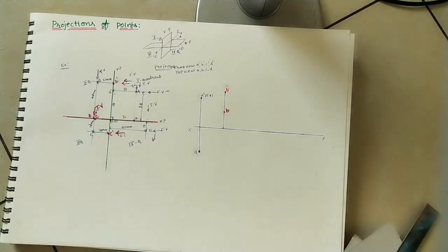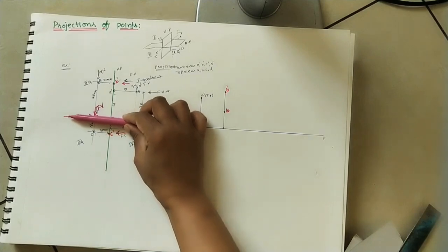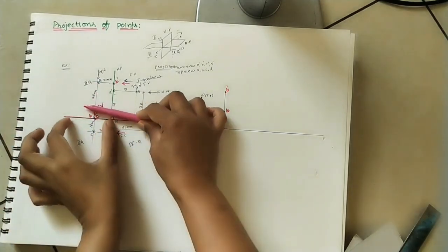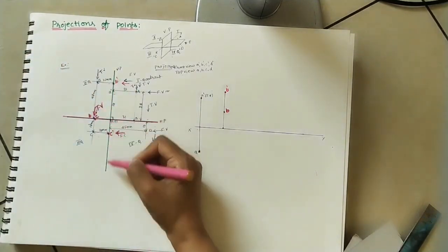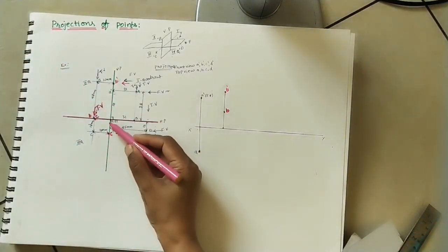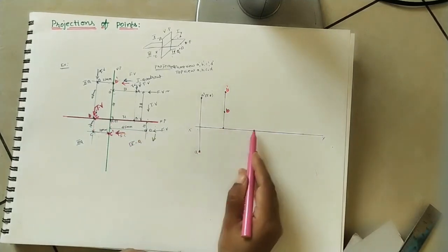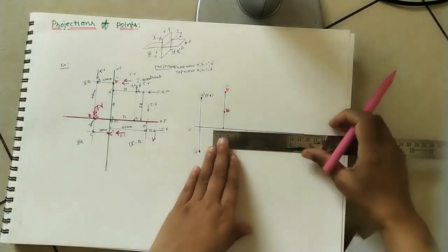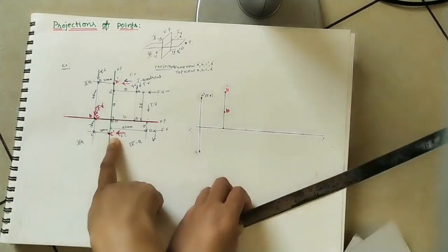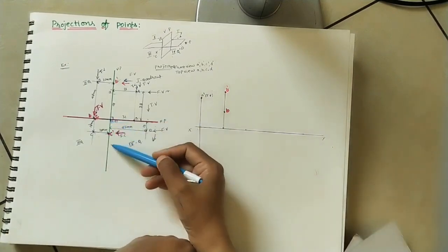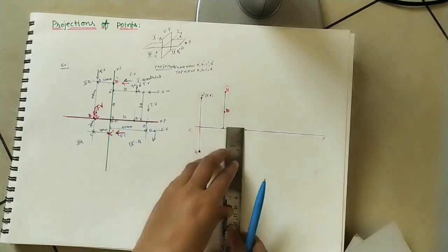So for doing the 2D view here, what I told, we are tilting this horizontal plane in clockwise direction. This part will move in upward direction like this. Okay, this plane is as it is. So C dash we have to mark same as it is. How much distance is it? 18 mm. So give some gap here, equal distance. So mark C dash initially. So it is coming below HP. Okay, so it is 18 mm.